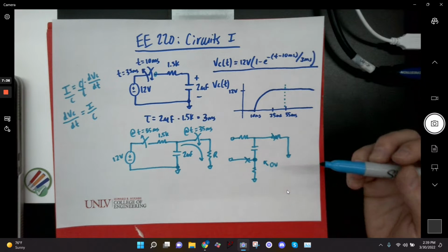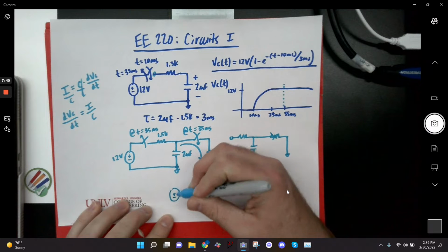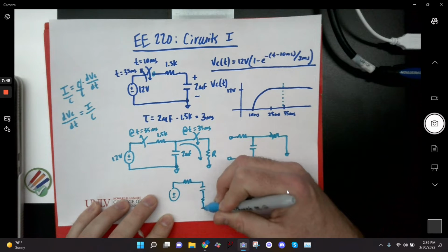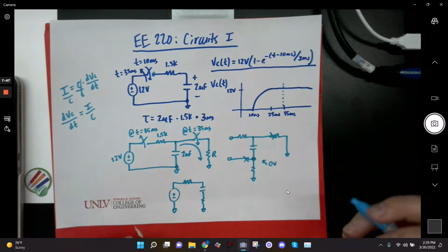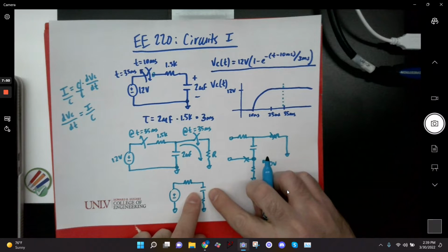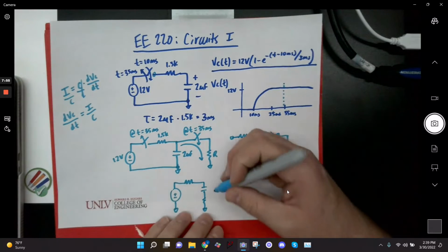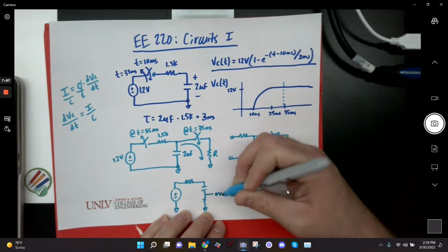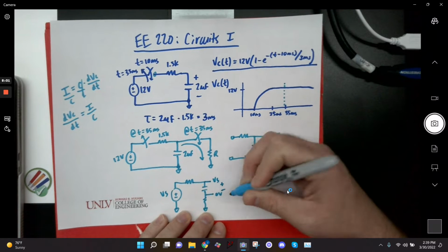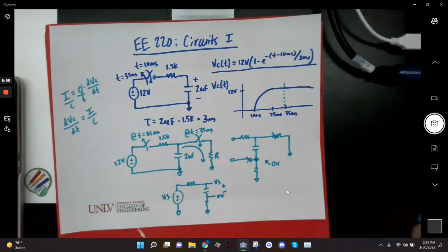Oh, really? Yeah, if we were to draw a circuit like this, so what you're saying is I've got a cap and then I've got a resistor. This changes how the capacitor charges. It's also going to change how the capacitor discharges, and basically in steady state we'll have 0 volts there and we'll have whatever my supply voltage is here. So my voltage across the capacitor will be my supply voltage, just like we're used to.